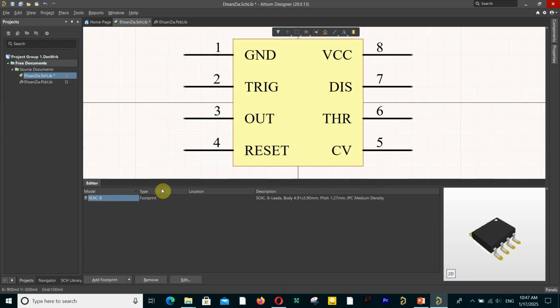You can see it here. So this is the schematic, this is the footprint that I added, and as you can see, you have the footprint and of course a 3D of this device. You can just hit save, and whenever you upload it in your new schematic, in your new project, you can have the schematic and footprint together. Okay, in this way you have the full package for one specific device when you want to design your circuit in Altium.